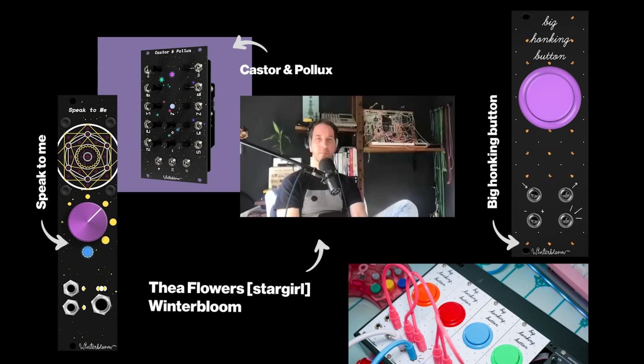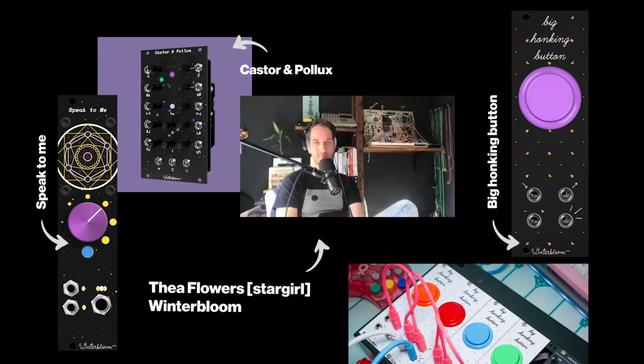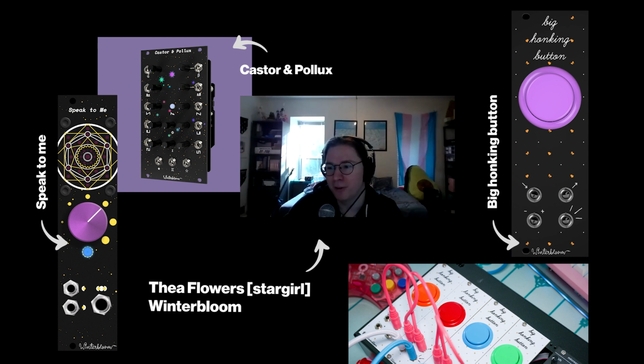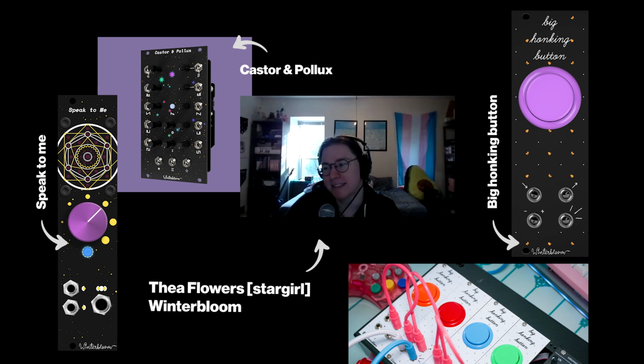It's a lot of stuff like that. You think you're done, and then you just find one thing that doesn't work quite right. The last revision I did literally added 2 identical resistors in the signal path, and they're not strictly needed. They're just there to help the module not go into a bad set of behavior if someone does something in a very particular way. Essentially, they're there to make sure the module doesn't overheat if you plug a mono cable into the stereo output jack, because by doing that, you actually short the right output to ground.